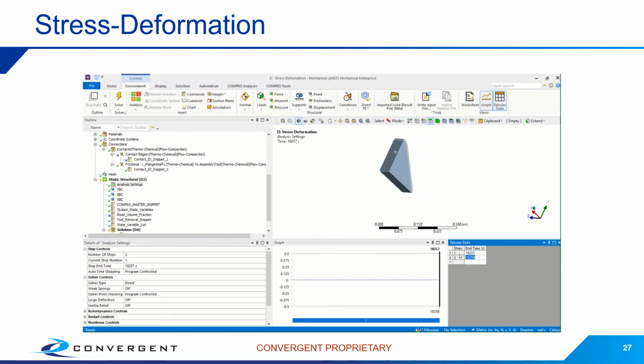The second step is tool removal, because of course to predict process-induced deformations, we need to predict how the part is going to spring in or deform when it's off of the tool. And the way that we do that is actually by removing the contact. So in the first step, we simulate the cure again with applied pressure and temperature cycle. And then in the final step, we delete the contact. So we allow the part and the tool to move through each other. And this simulates demolding. So obviously when you demold, there's no interface between the part and the tool.